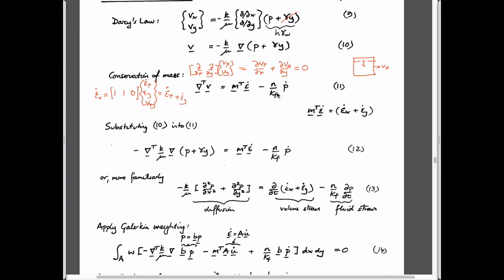the volume. And if you alternatively just change the fluid pressure and don't allow the boundaries to change, this is the amount of makeup fluid you have to supply to be able to keep them the same. So this acts with a positive component because you're squeezing it with positive strain and the fluid goes out. The other one is negative because you're keeping the volume of the thing closed, you're changing the fluid pressure, fluid shrinking, so to be able to keep that volume filled, you have to add water to it. So they occur with different signs.